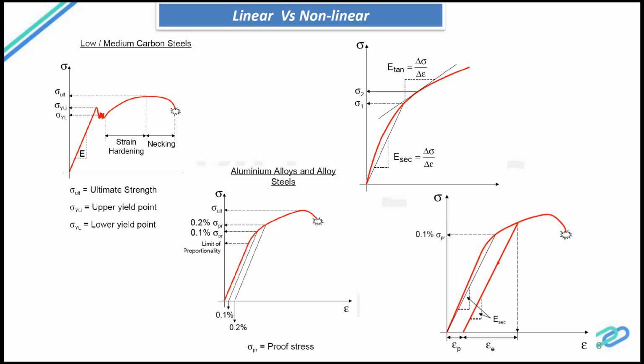But this whole region is still under elastic stress, but the behavior might be non-linear above the proportional limit. Once it crosses the proportional limit, the behavior changes to non-linear elastic, until it reaches the yield point. After that, it is fully non-linear. So the entire region is elastic from the permanent set. So the total strain would be the strain caused by the permanent set, which is plastic, and the elastic.